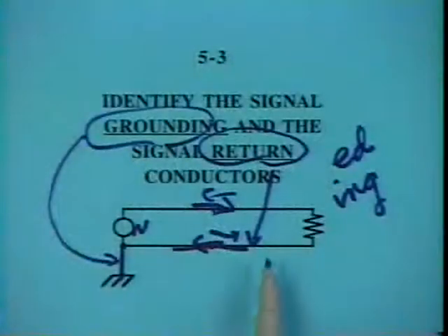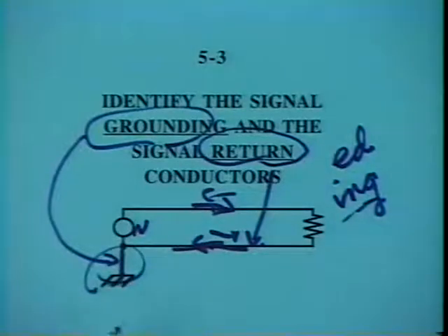The words represent ideas, our concepts, our strategies that we're trying to implement. If we've got the wrong word, we've got the wrong idea in our mind. So it's not just semantics. It's a lot more basic than that. And safety people, they know the difference between a grounded neutral as opposed to the safety grounding conductor. They make a big difference between those two. So this conductor, this is a grounded conductor, but it's not the safety grounding conductor, which is this one over here.